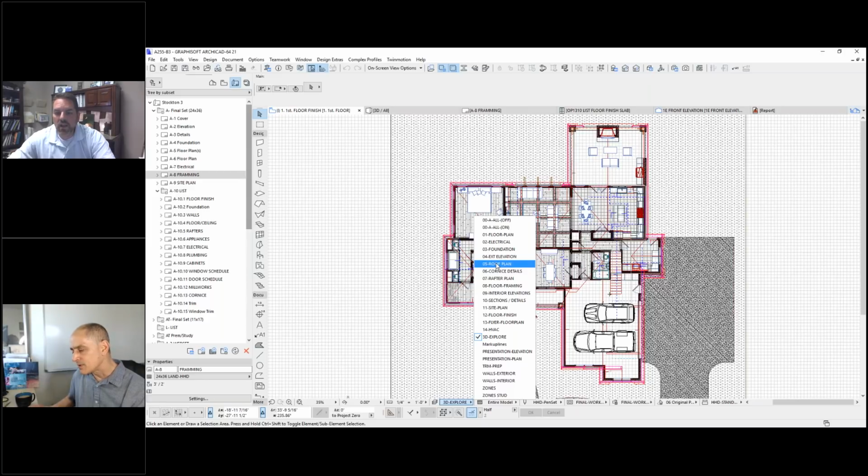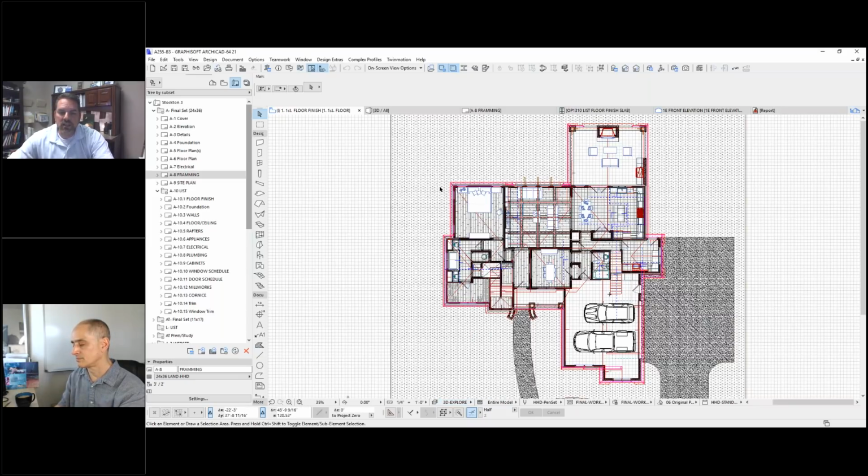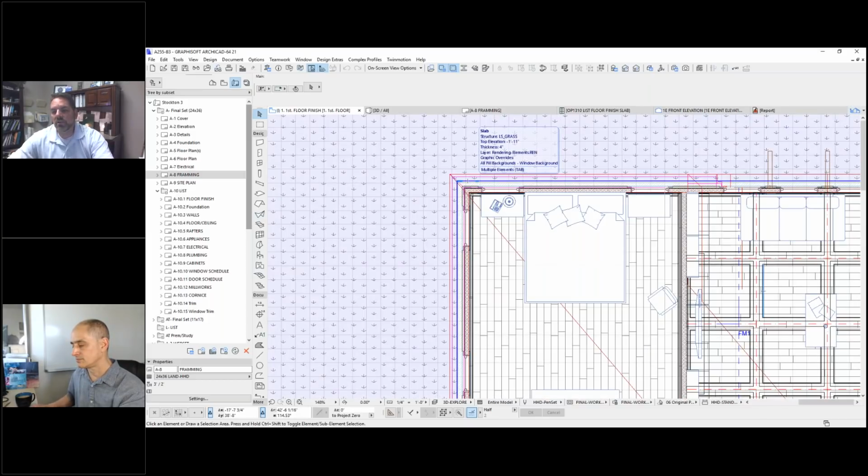complex profile? Yeah, complex profile for brick rowlock, but I used it until they updated ArchiCAD so you can actually take off quantities from a complex profile. So I'm starting to get more into breaking those calculation surfaces down, as opposed to before, when it always took off the one solid element, even though you had multiple elements within your complex profile. But that's exactly what that is. The brick rowlock is a complex profile, and it's separate. I just use it as a brick rowlock itself. If I go to